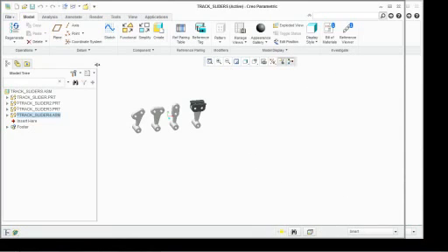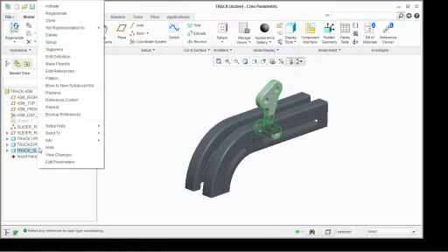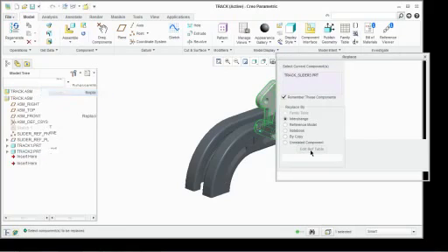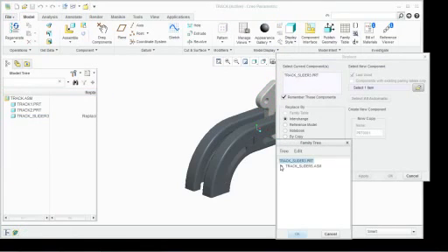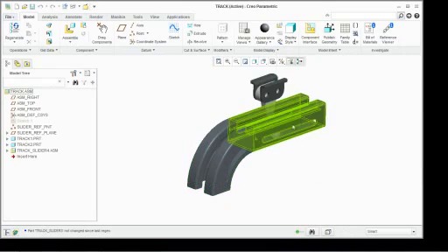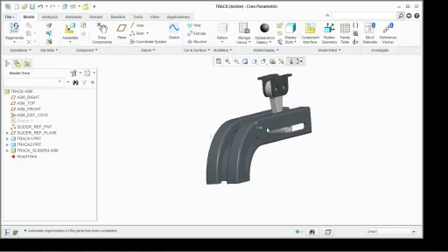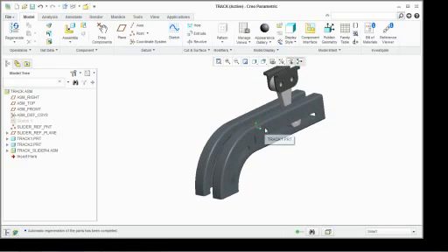And we're going to flip back over to our assembly, to take this track slider 3. Oops, don't want to hide it. I want to replace it with an interchange, and this time I want to expand this out. Notice it's showing me 1, 2, and 4 because 3 is active. It's not showing me 3 because 3 is already there. So I'm going to select 4, click OK again, and notice it changed, and I can move this point just like before. Say move it back to point 1, and it's a functional part of the assembly just the same way.